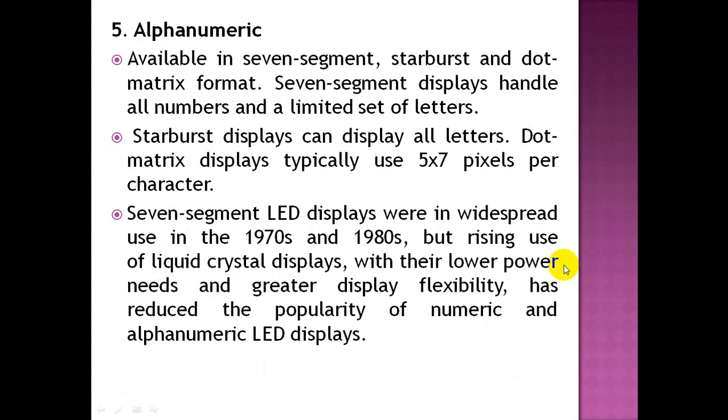Next is alphanumeric, available in 7-segment, starburst and dot matrix format. 7-segment displays handle all numbers and a limited set of letters. Starburst displays can display all letters.